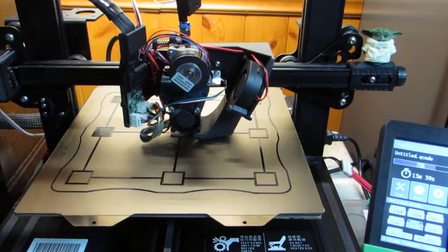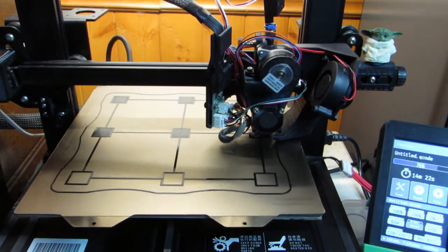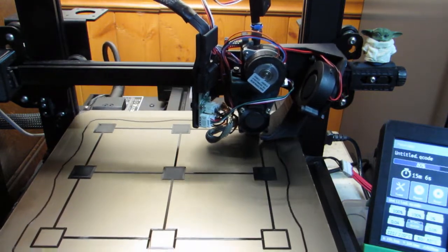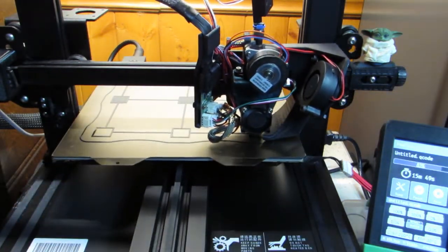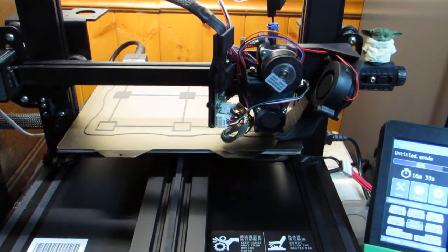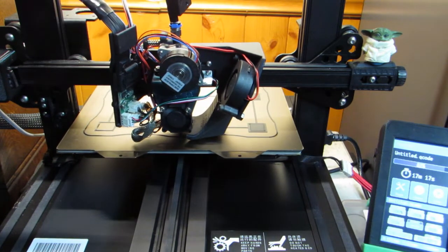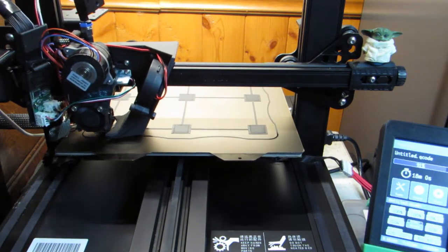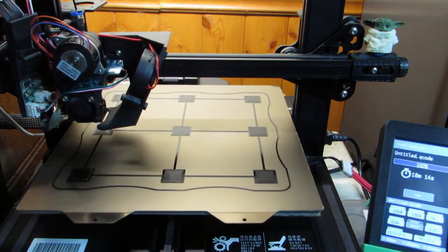So what you see here is the slicer has drawn the walls around each square first, and now it's going to draw the bottom layer of each square, there only being one layer. We're not seeing any scraping of the pattern or places where it simply didn't print to the bed because there wasn't enough distance. So I like to interpret that as the offset is not too low. And there we go.